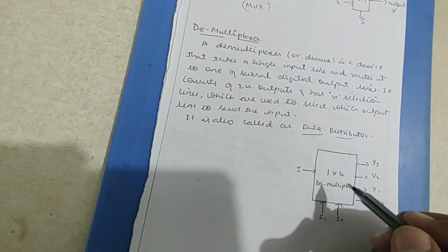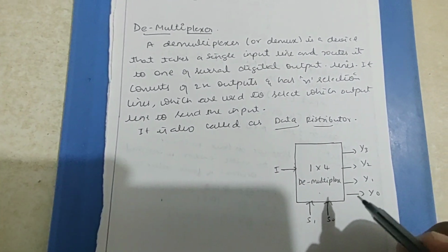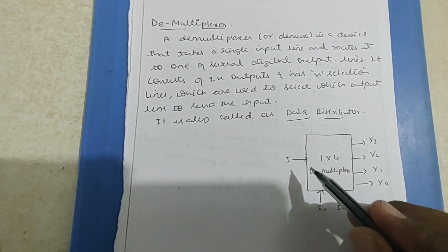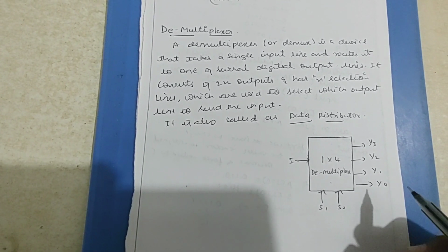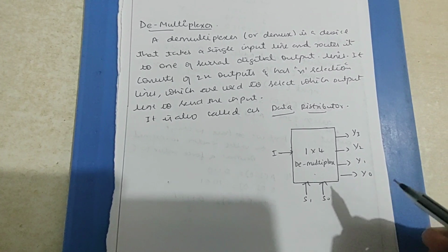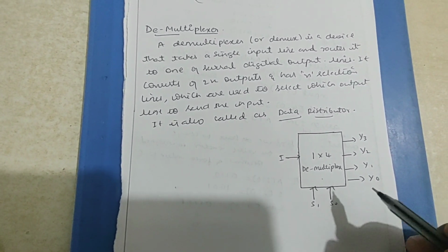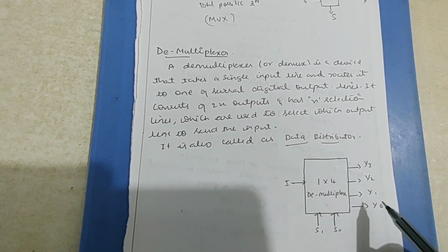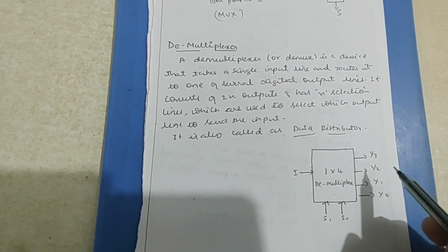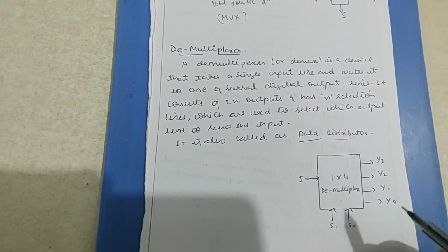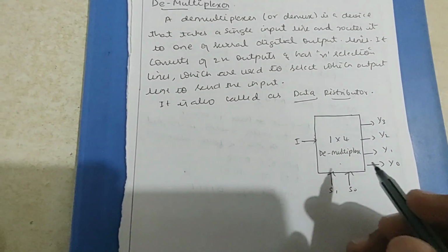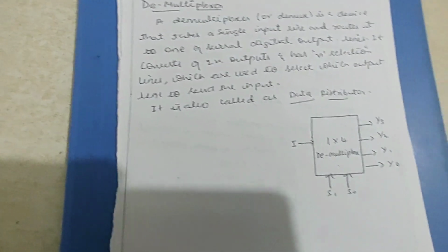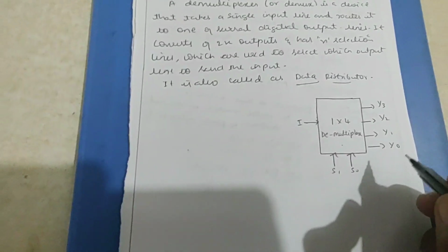The demultiplexer we have chosen here is a 1:4 demultiplexer, where I is the input, and S1 and S0 are the selection lines, with the values 00, 01, 10 and 11. We will get the outputs y0, y1, y2 and y3. Demultiplexers are used in several applications with multiple inputs and outputs, in data routing and several system controls, and can also be called a data distributor.